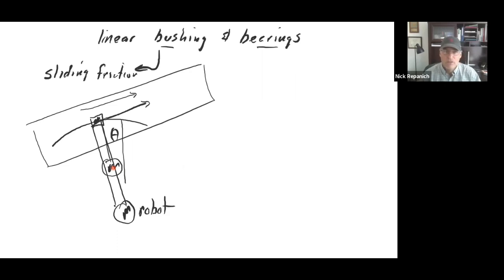And that's what I would do: I would go buy the math from a robot company. If you're going to build your own polar coordinate mechanisms, then go buy a controller where you can put in the distances of each arm and what you want them to do, and you buy the kernel that does all the inverse kinematic calculations.